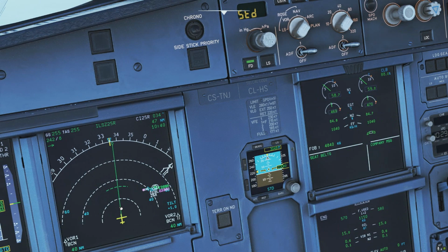Another thing, as you can see here, we'll be approaching the runway from the opposite side. The plan is that we're going to turn right here at some point, fly downwind, and then join the ILS. This is actually quite good, because for descent planning the general rule is abeam the runway, make sure you're somewhere around 6,000, maybe 7,000 feet above the runway.